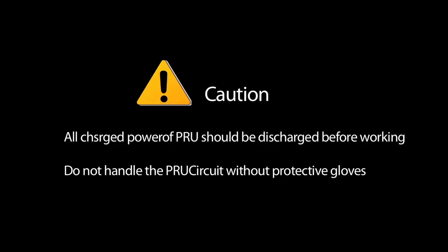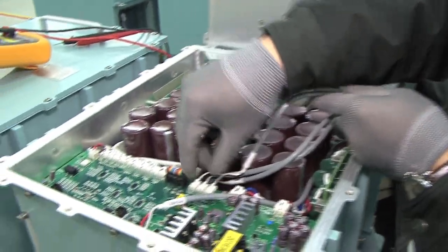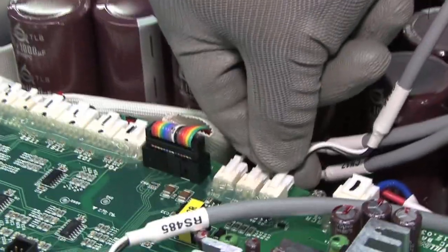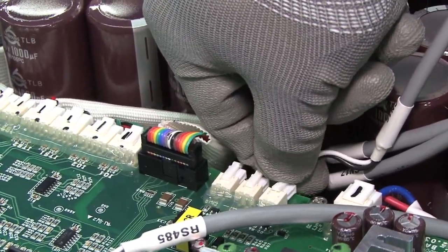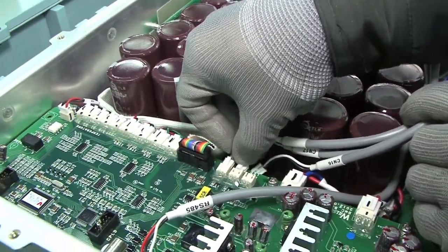Rectifier lamp. Applicable equipment and location: PRU. Step 1. Remove the top cover of the rectifier by unscrewing bolts. Please do not open the top cover completely until Step 2 is finished.